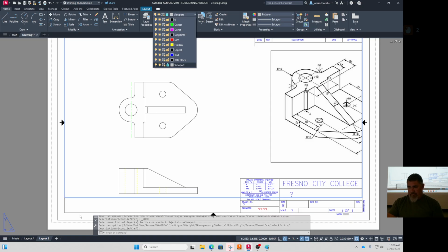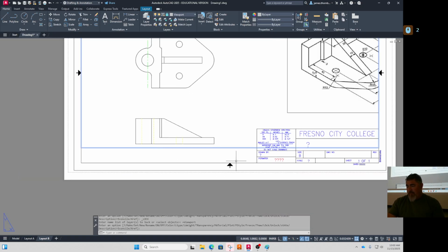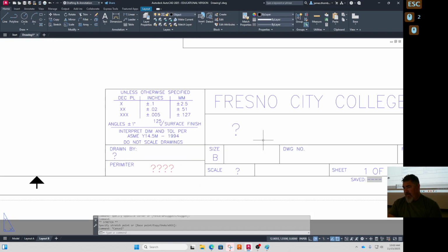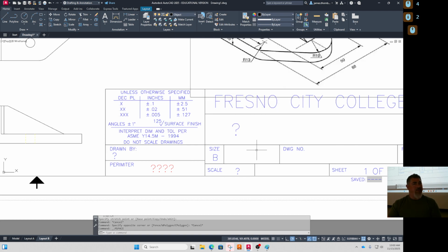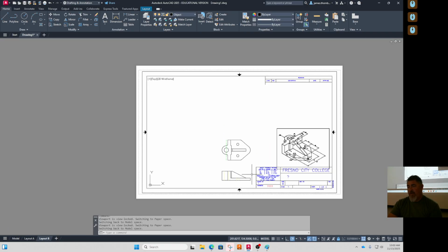I don't like to have it all the way on this line, because if you accidentally click when you're doing that stuff in your title block, you can click into the viewport and then you're stuck. So like if I had this all the way down and I was looking in here and I went to go change this, but instead of clicking there, I clicked here. Now it's doing that, right? You can see the viewport scaling behind it, but I'm kind of stuck. I think some of you did that when you were making your templates. So an easy way to get out of that, just lock it here in the bottom right. Now I can zoom out.